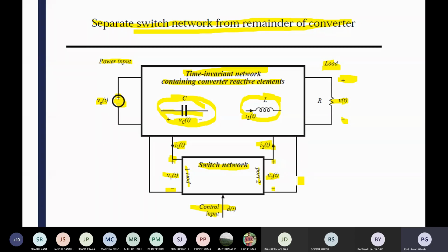In the Simulink module, you can directly drag blocks. A transfer function block, a generalized transfer function block, is also there. Now you can give the denominator and numerator values in matrix form, which you can get from your M file script. So you can represent your switching converter in the form of a transfer function.